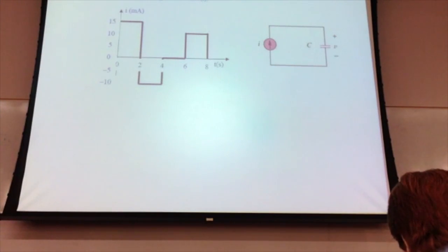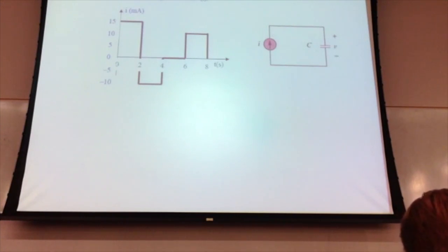If I make this thing over here time varying, a sinusoid, 110 volts going at 60 hertz, I will then induce a magnetic field into this coil of wire of the same frequency, 60 hertz. What happens over in the second coil of wire? I'm going to put a little load out here. This could be your house. I'm going to now induce into this side over here another current. I will then get a current coming out of here.